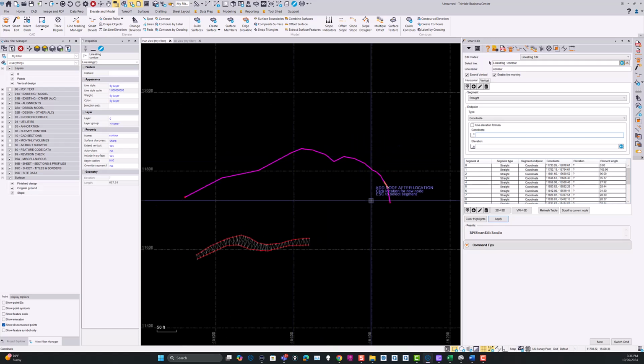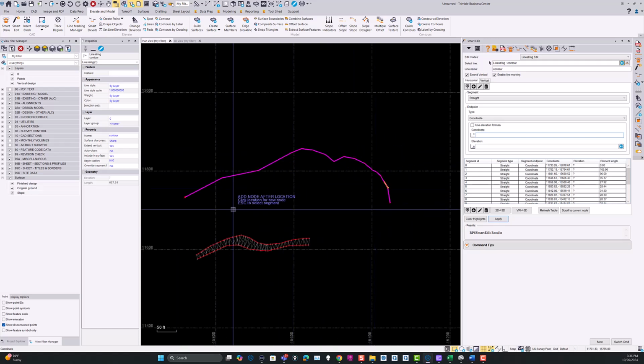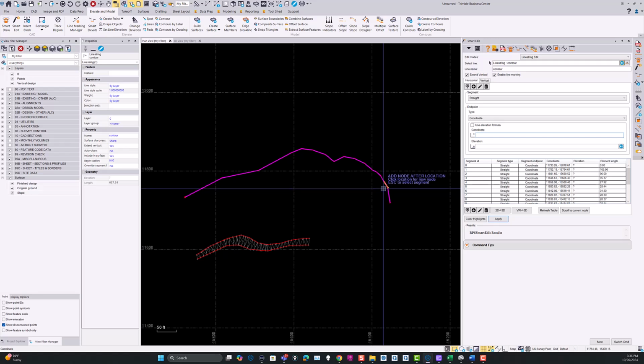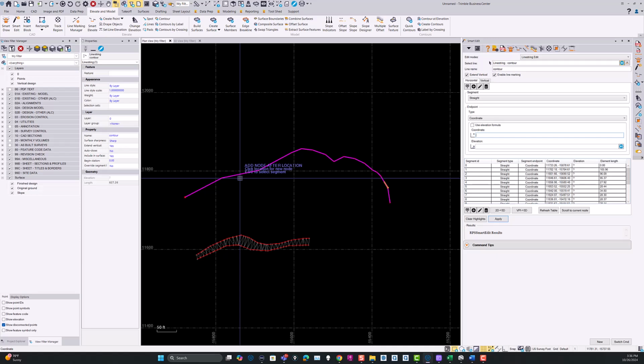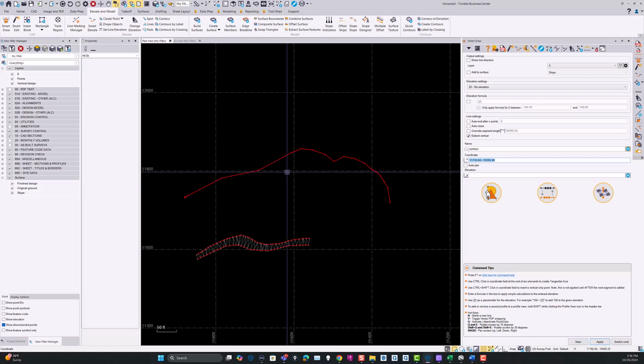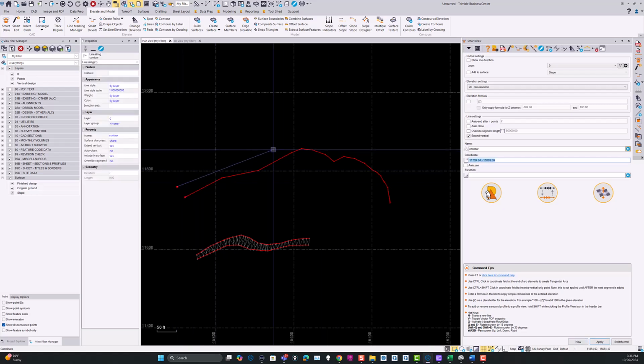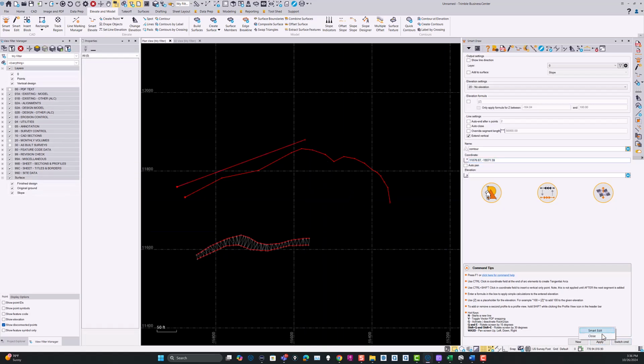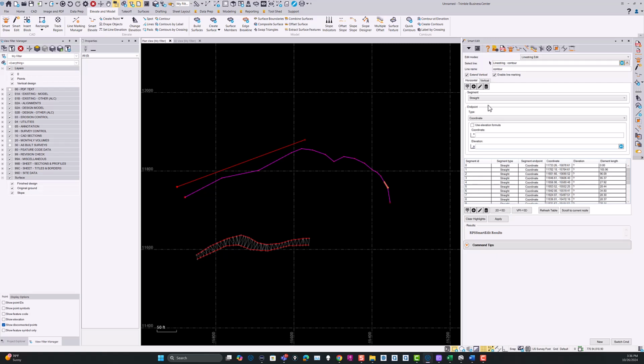So this is a quick and easy way to edit line segments and line nodes in either 2D or 3D. If you wanted to add points using station and offset in relationship to another line, again, I go back to switch command and go to Smart Draw one more time here, and let's say I want to draw another 2D line, just start a new line, and draw it from here to, let's say, here, and then say now I want to switch back to Smart Edit.